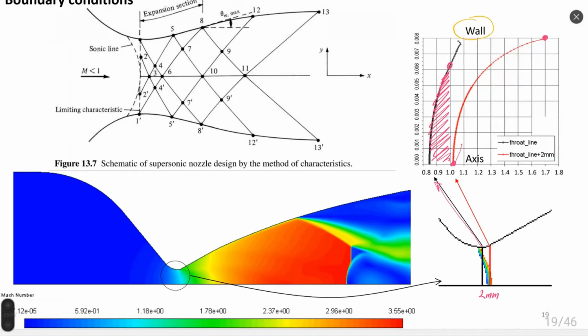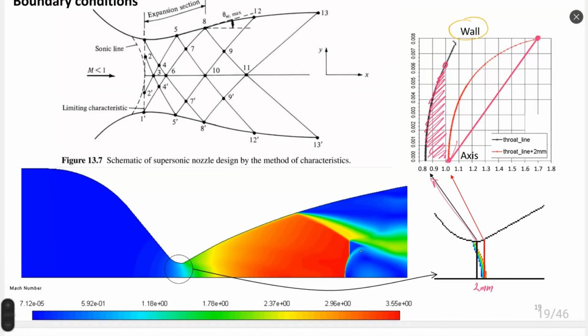Or have some preliminary simulation to obtain this distribution of Mach number along the radial direction, or just select some constant value, for example, in the middle, 1.2 or 1.4, for all points near the axis, and on the wall use the same value. Not so important for the final calculation, in my personal opinion.